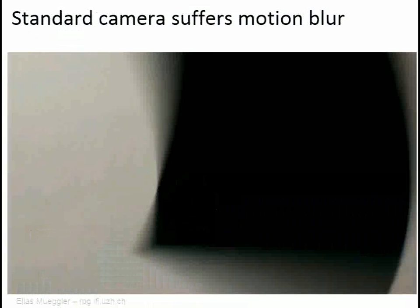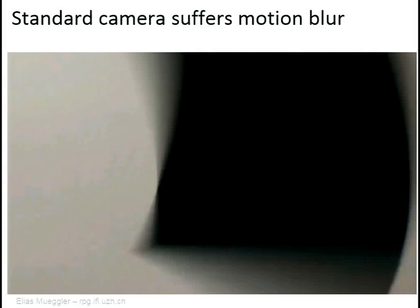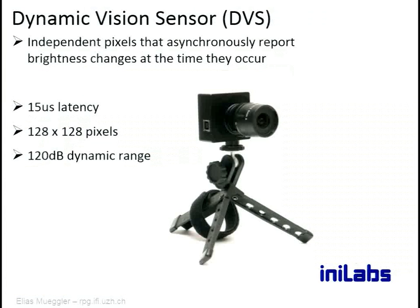So when we look at the front-looking standard camera of that quadrotor, we can see that the images suffer from heavy motion blur effects. So we try to overcome this limitation by using a different vision sensor, namely the dynamic vision sensor. This revolutionary sensor has independent pixels that asynchronously report brightness changes at the time they occur, with a temporal resolution in the range of a few microseconds.